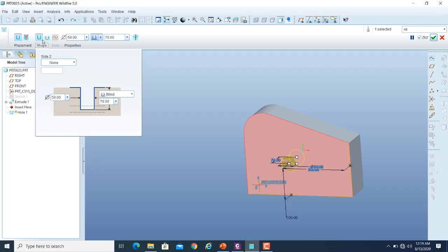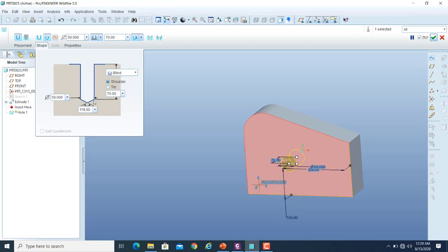And within that you have two sub options, like this is the first one. If you want to make the end face of the hole as a plane surface, so you can use this option, or you can make it as a tapered section also. So you now look at the cross section आपका जो, for example, so if you really want to machine that whole feature within the block using the manufacturing module, so वहाँ पे हम twist drill use करते हैं, ठीक है ना. twist drill का अगर आप point देखें, so that is conical in cross section, and normally the standard angle is 118 degree for that.